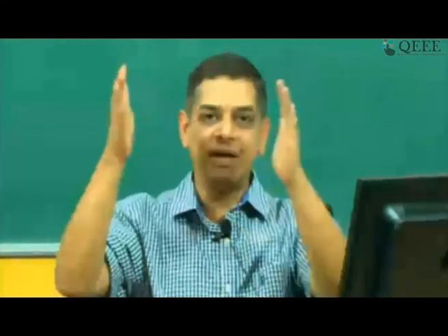Okay. Shearing in plate, I think it is shear buckling of the plate that Tamilar C has asked about. So in shear buckling, because of the complementary shear, you get one diagonal in compression and the other diagonal in tension, and as a consequence that compression diagonal can buckle in shear, but the tension diagonal continues to carry tension. So the plate as a whole continues to carry more load, more shear.